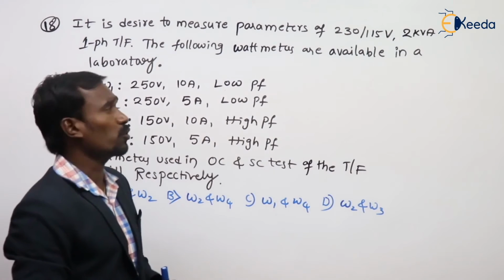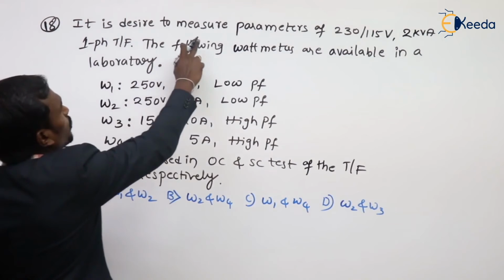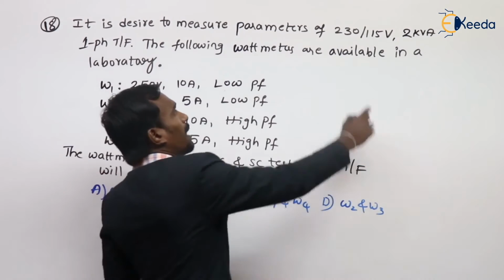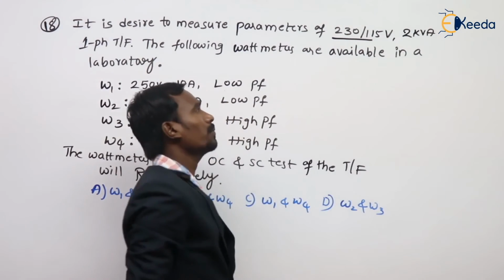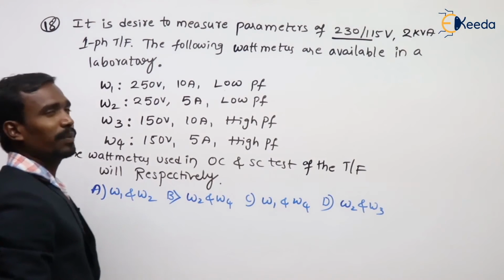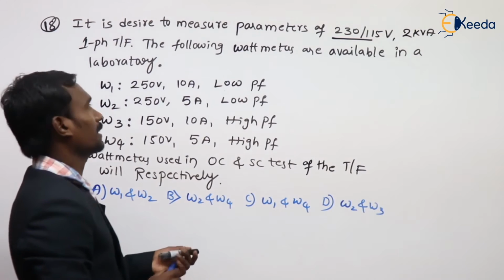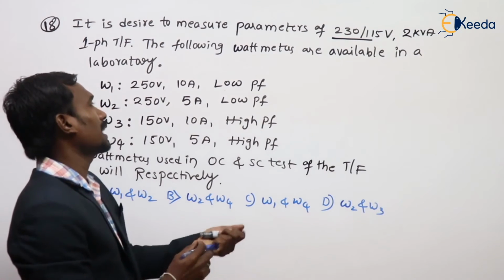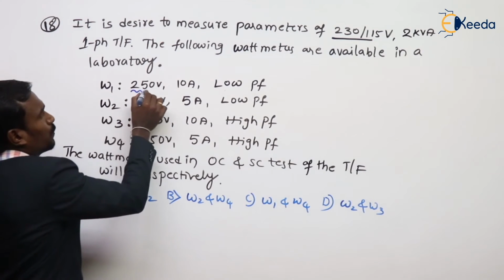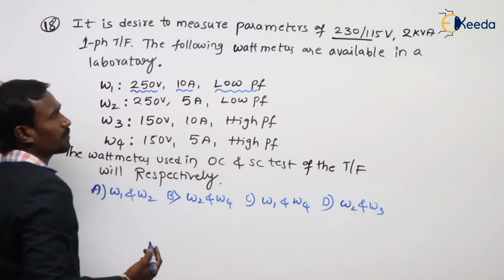In this video, see this question on testing again. It is desired to measure parameters of a 230 by 115 volts, 2 kVA single phase transformer. The following wattmeters are available in the laboratory. First wattmeter: 250 volts, 10 amperes, low power factor meter.